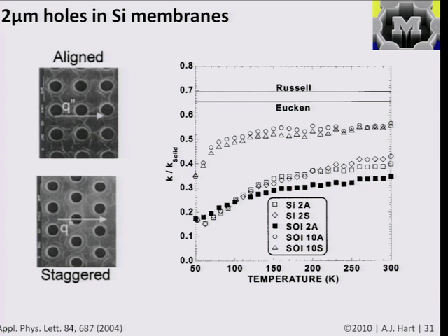And then using basic Fourier theory, like if you were to put this in a finite element simulation or just solve the diffusion equation, for each of these cases, you would get these two limits for what the heat flow across that membrane should be. But when they actually measured it, they found that it was significantly lower, by about the fraction that you would expect from phonons with those long mean free paths getting cut off or disrupted by these holes. So even though these are micron scale holes, you start to see some ballistic effects and reduction in thermal conductivity.